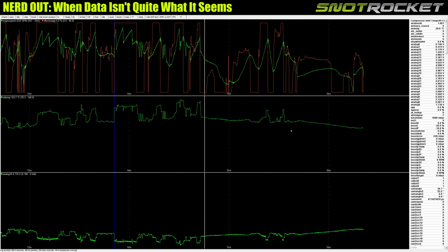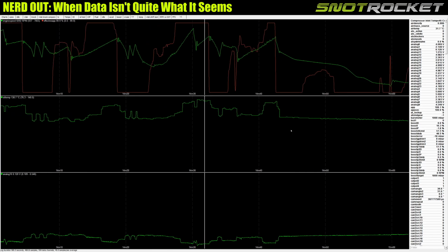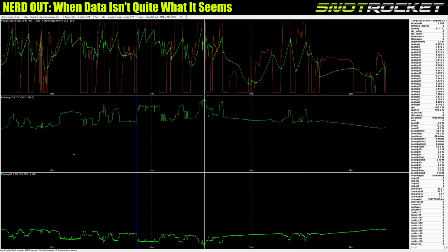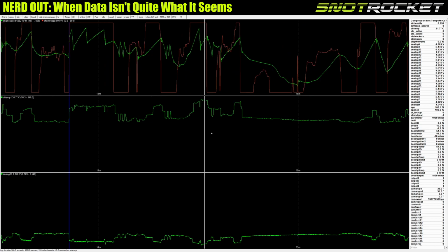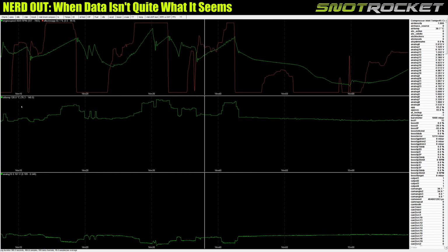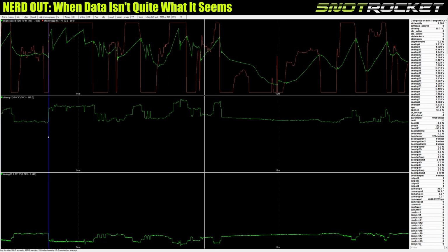If you look at the peaks here, oil temperature is getting up to supposedly 140 degrees, which is too high, really, for the oil I'm running, using it on track. What is much more appeasing is if I look at the temperature after you come off VTEC here, it's 126, which is much more expected on track and in engine use.